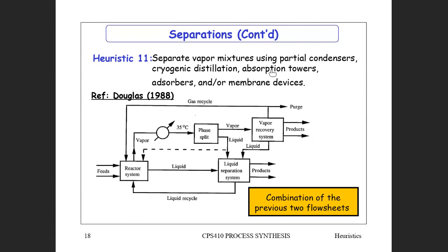The trouble with an absorption tower is, let's say you're using water to strip out one of the gases. You've still got to separate that with liquid distillation. But liquid distillation is a relatively simple unit operation, so that doesn't bother you. But separating gases is always difficult. So certainly you'd want to do absorption if you could.